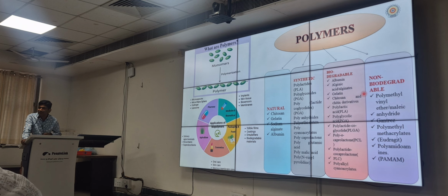So likewise, if we talk about the bone, whatever the biodegradation rate is, it should not be very fast. It should be a minimum of 6 months or beyond. But if we talk about the skin, it should not be 6 months, it should be very fast. So based on the applications, we have to make the right choice, right? For example, many research papers have come up that claim a material is used for the skin and also for the bone. Then how can we play around with these materials? We have to make some kind of composites. We have to reinforce it so that it degrades at a very slow rate, so that we can apply it for bone. Otherwise, it is for the skin.